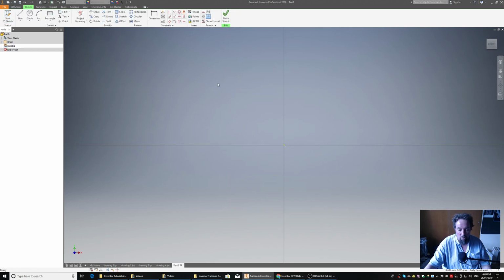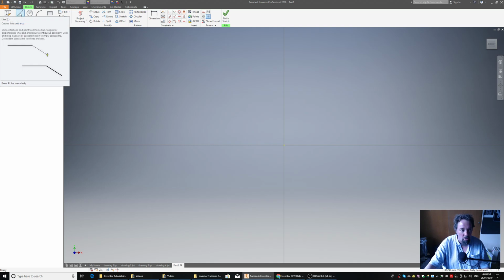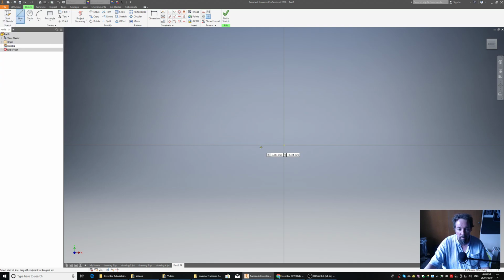And just like we did in drawing 4, I'm going to show you how to do it using the line tool and then using the dimension tool. So the line tool is right up next to where we saw sketch. Come down to the origin, which is the center point where it goes green, click. Draw the basic shape, click. Remembering just to make sure things are 90 degrees.